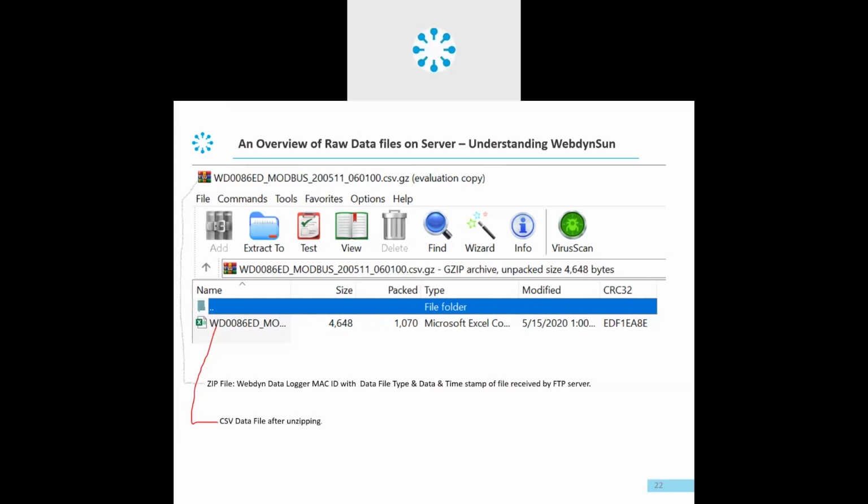But if it is TCP IP devices, certainly it's possible. If it is RS485, again you have to see if you can fix the baud rate to the maximum, so that the communication can be faster between the devices from the chain to the Datalogger to the master, by the time the timeout happens. At the Datalogger level, there is no limitation for this timing. Similarly, the connection time to the server is again configurable.